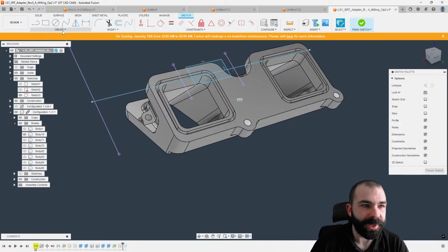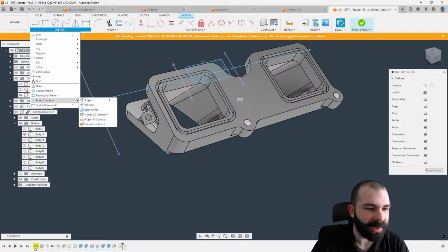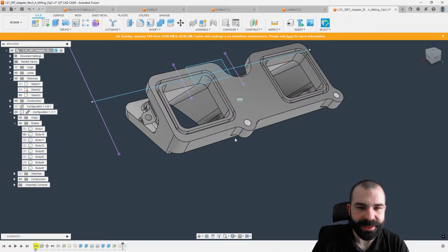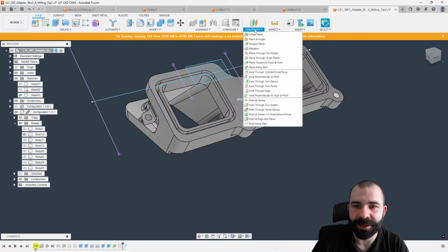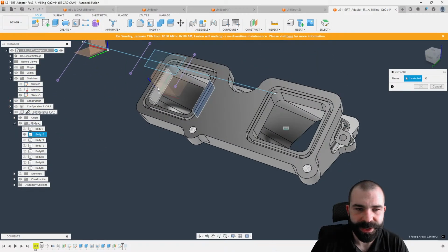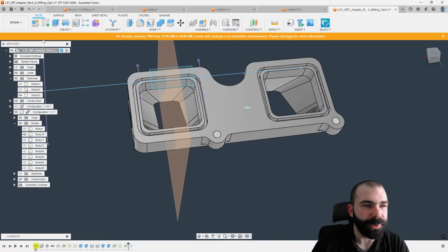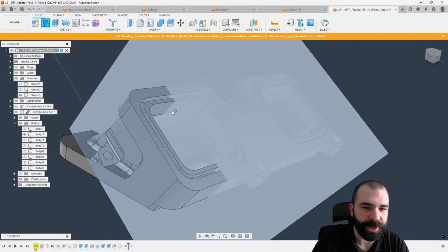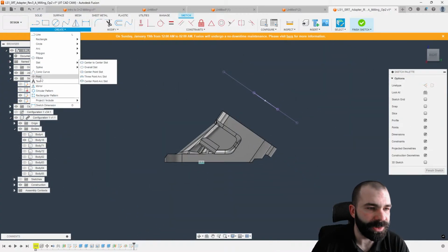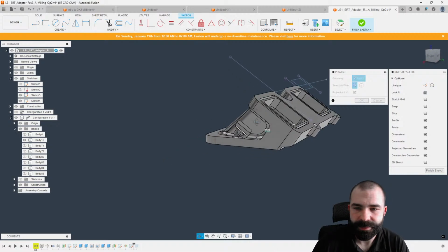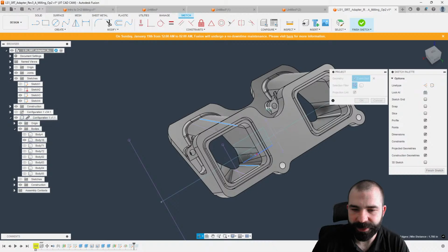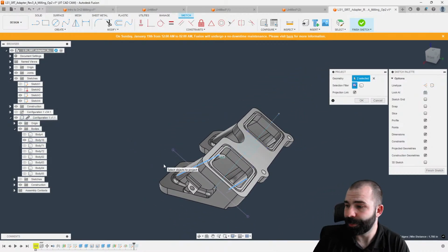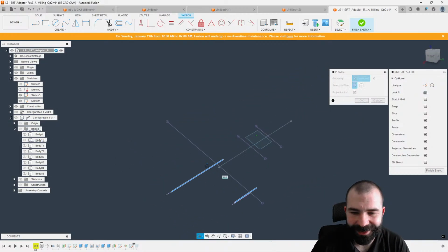So what is happening is we need to use a project, right? And what I really need to do is create a new plane for my sketches. Actually, let's make this really fancy. You guys are going to learn today. I'm going to do a mid plane in here and here. And I'm going to create a sketch on that plane. And then I am going to now project some lines. So what he's thinking is with this line here and roughly this line here, it'll get better in a minute. Bear with me. Get the model out of the way.